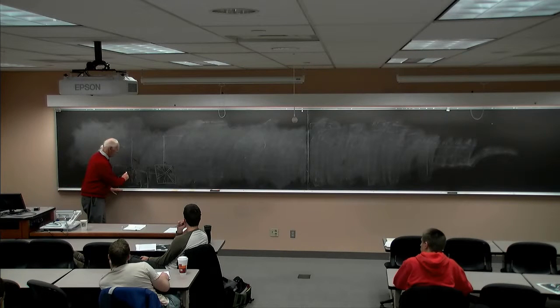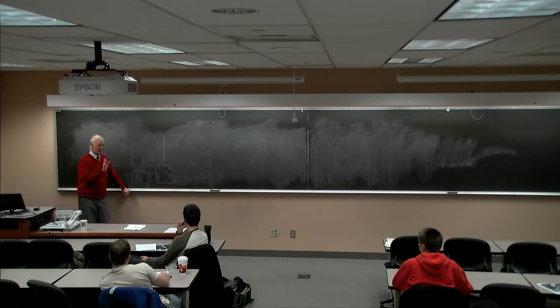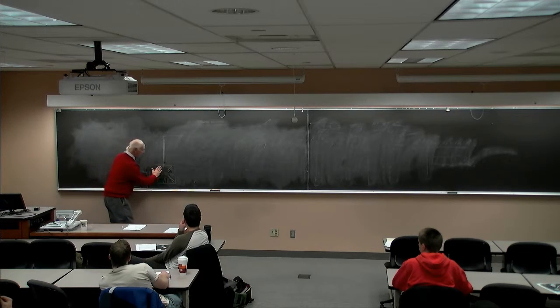When the B field is not there, there's nothing happening, of course. But when there is a B field here, and there is, guess what, velocity, the B field is constant. So this is the case where if you look at it from the Lorentz form, that first term, there's no rate of change of B with respect to time. That's gone. But there is the velocity term, V cross B dot dl. Like that. So what was happening was, let's say in the solid plate, when that velocity was moving along, there was voltage induced in here.